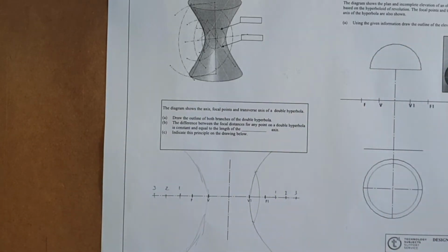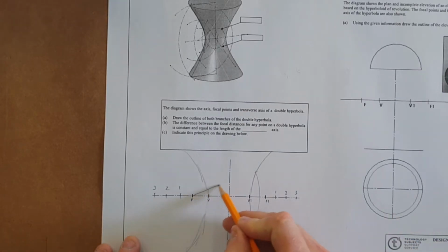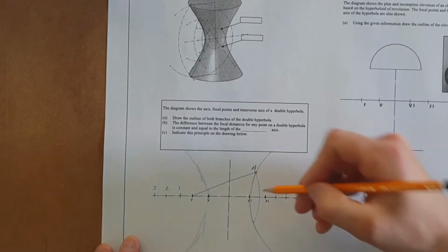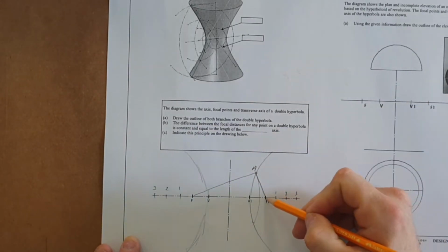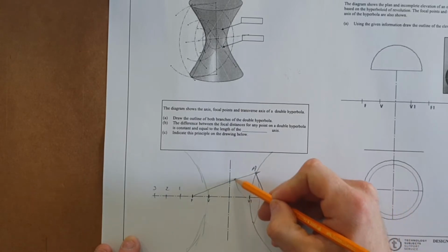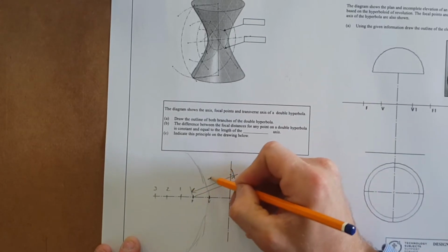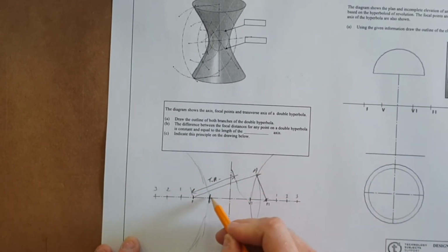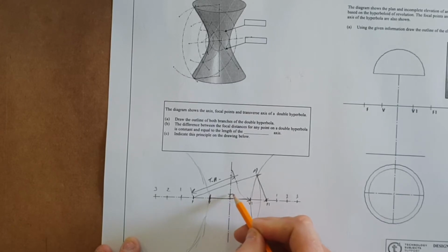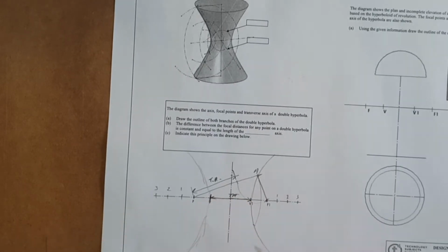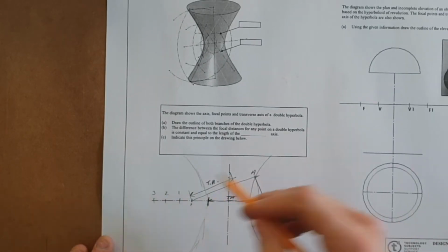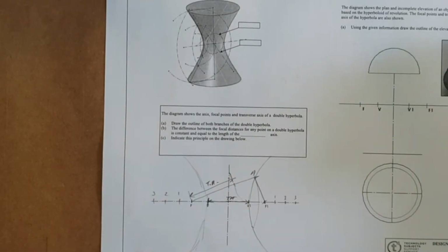Okay, and don't forget as well, just as another point of note, from the focus to any point on the curve, we call that point A, and back to the second focus. If you subtract the distances, so take the distance of the small line away from the large line, we're going to be left with that right there, which is the transverse axis, which is the very same as the distance between the vertices, the transverse axis. And all of the stuff that comes with that, like the auxiliary circle and the asymptotes and so on, that all comes after. Now that's structural forms sheet 2, on to number 3.